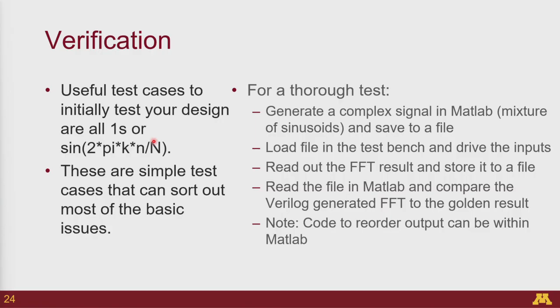The reason I'm bringing this up is that these tests are usually very easy to implement. All ones is just connecting the input to one in your test bench, but they can eliminate almost 90% of your bugs, right? Because the beauty or the complexity of the FFT is that if you have a mistake, it propagates throughout your entire design.